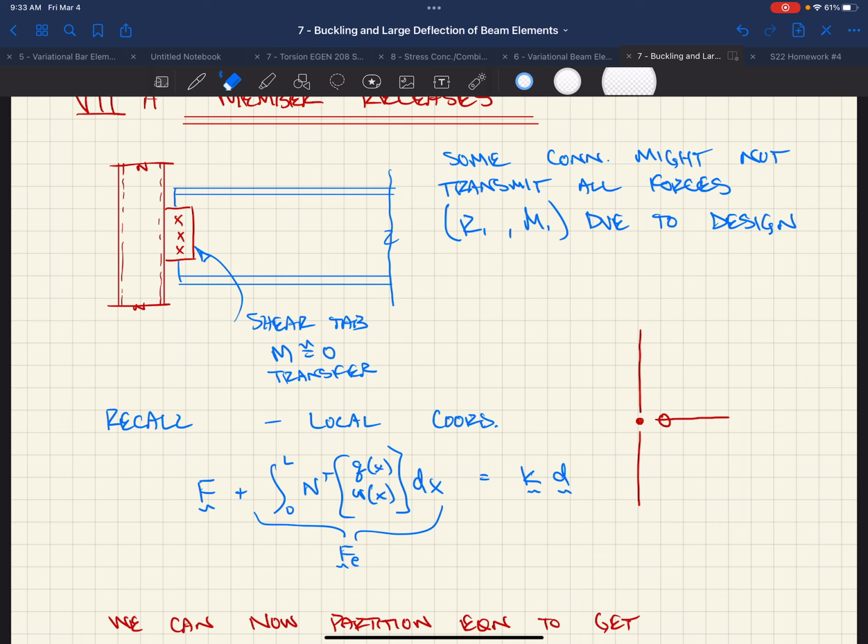So then you have truly flexible behavior. You have this continuous beam model approach that you could do, right? You essentially look at, say, 3 frames in series and the diaphragm extending over all 3. That one in the middle you could assume is like a support on a 2-span continuous beam. That's going to give you a different answer than if it was a simply supported beam, like that would be our flexible diaphragm approach, right? Or then you step a step further and the code allows you to just do full rigid, right? Assuming that it does not displace at all. It's perfectly infinitely stiff, which gives you different answers still.